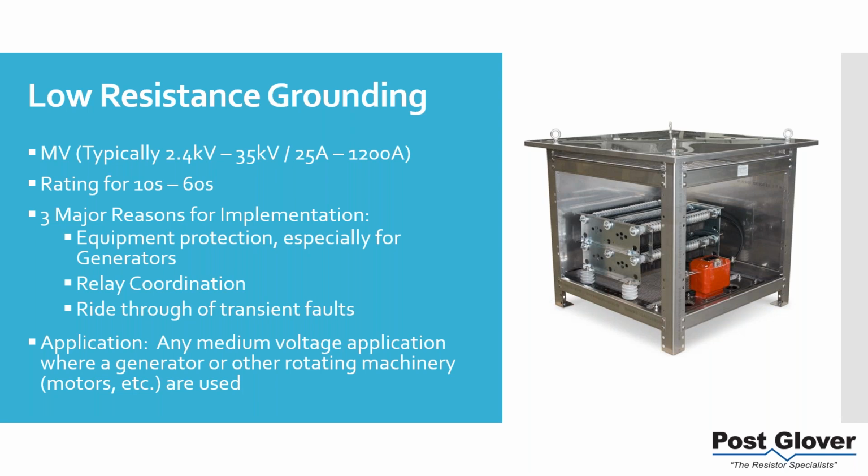So if I have a fault on a local motor, and obviously on a solid ground system there's potentially lots of current flowing, you may trip instantaneously and potentially have a situation where your entire system is tripped. I've seen it happen. I get something like that at least once or twice a year, maybe a little more, in terms of installations where that has happened, and they usually change to a low resistance ground or high resistance ground system.